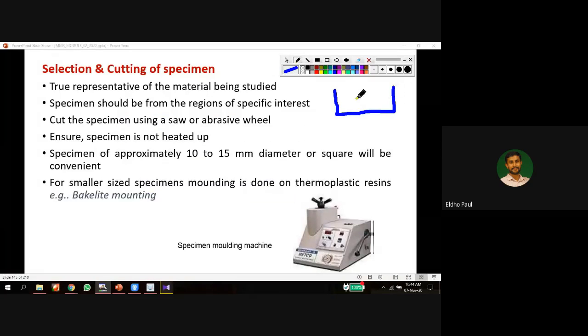In this container, I cast the product. While melting, this is the base metal or pure material, but these are the impurities or alloy elements, for example. There is a chance of high concentration of alloy elements in the bottom region.